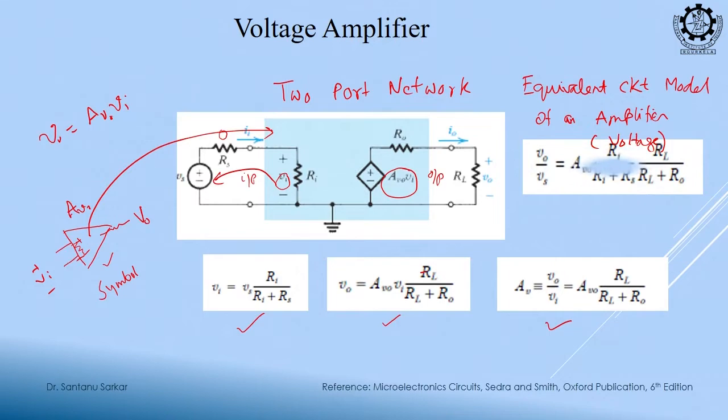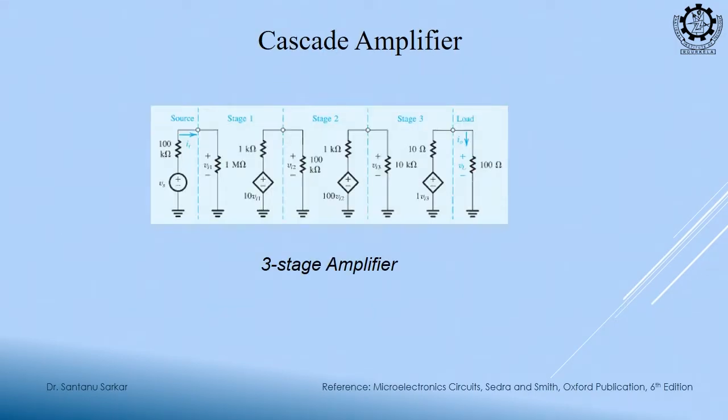Now, how many types of amplifier could there be? This is a multi-stage amplifier, where we discussed that several stages, 3 stages here, are connected in series, right. So, it will be just like this. Now, can you tell me what is our Ri requirement? The input impedance of a voltage amplifier should be infinity, very large. What is our output impedance requirement? Very low. So, in between we should have a high gain.